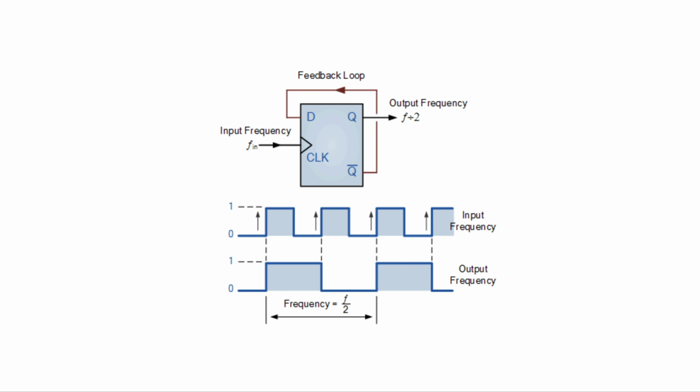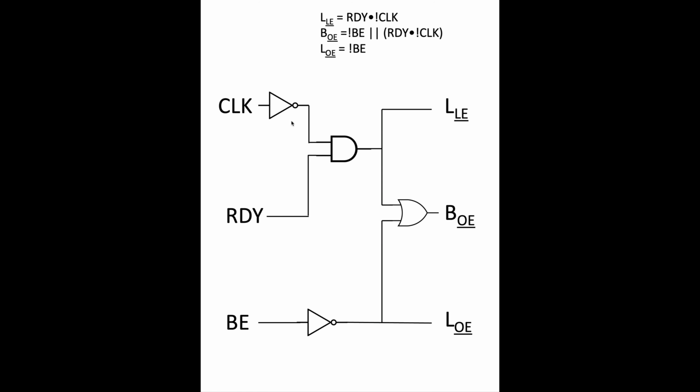So if we add this flip-flop to our clock generation, we can remove the inverter because we now have the inverted clock, and we know that the inverted clock is perfectly synchronized with the clock. So in terms of the timing, it should be much better.